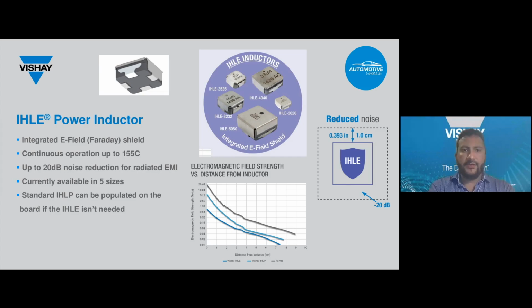This is another innovative design by Vishay. This is the IHLE. This features an integrated shield to mitigate electric field emissions that could result in EMC compliance issues. This shield also provides better shock and vibration performance than the standard IHLP. Also, it provides improved mechanical stability due to the 4 pads used for mounting.